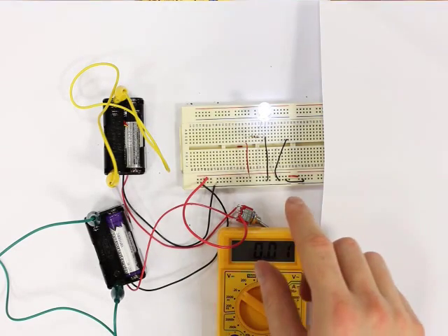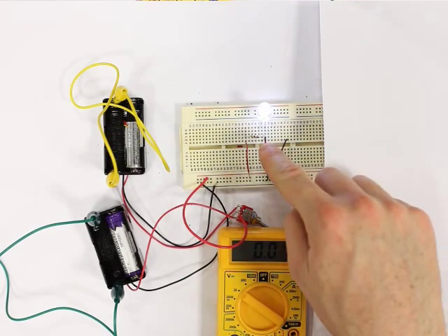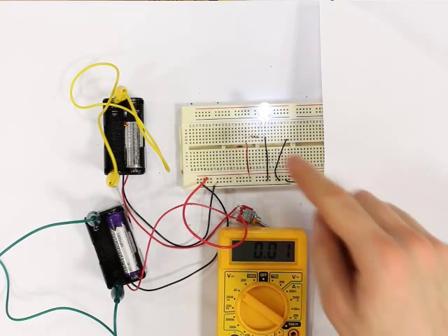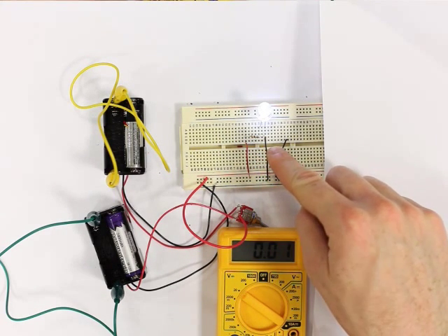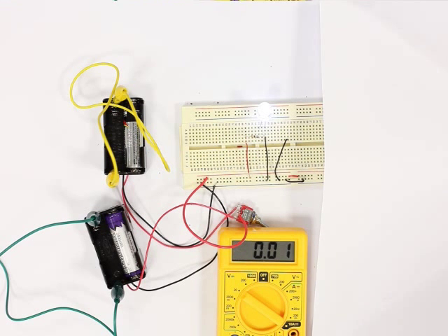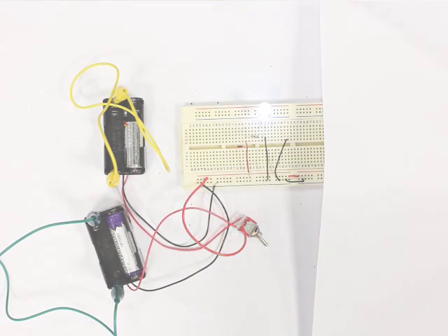So we can tell from that, because the current is the same through the resistor and the LED, that about a third of the power from the source is going into the resistor, and only 2/3 is being consumed by the LED. So our circuit here is really only about 70% efficient. So let's see if we can do any better than that.